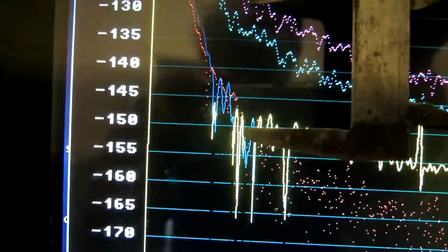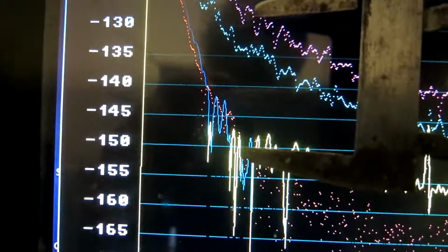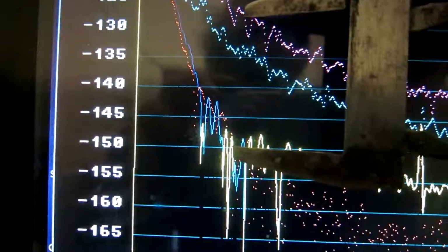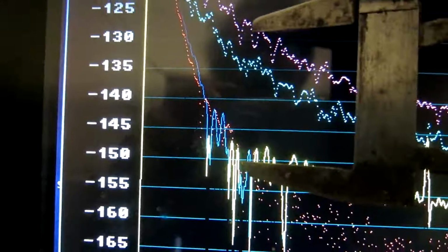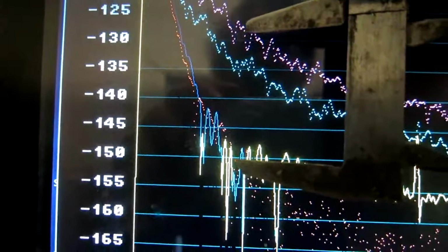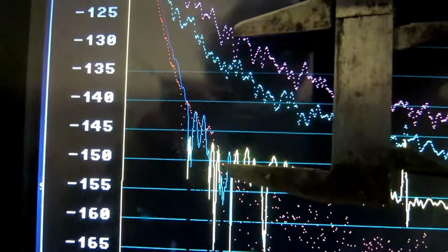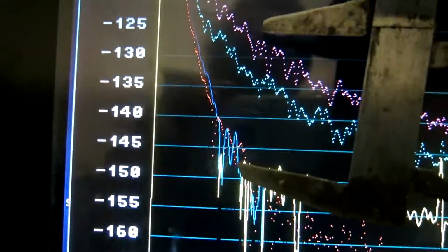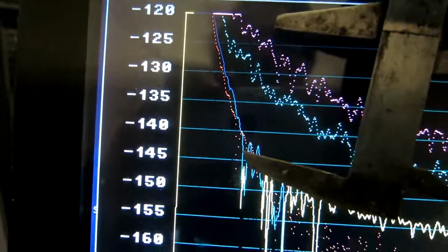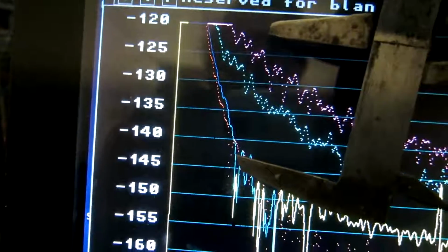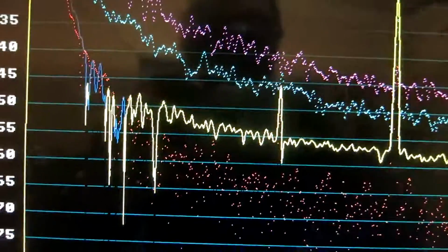And here, the random noise of the receiver itself, that sideband noise of my local oscillators, is as big as the expected correlation signal, or even bigger. So it adds at random, sometimes negative. And then at a little bit closer range, I have this problem that the oscillators are correlated somehow. So it is very slow.